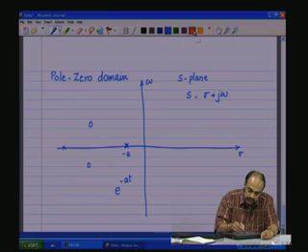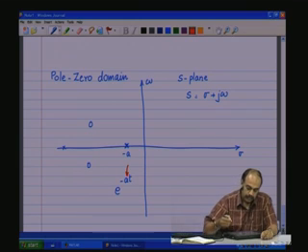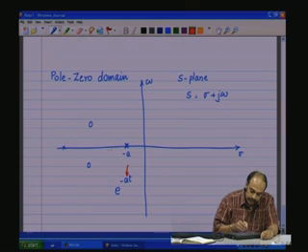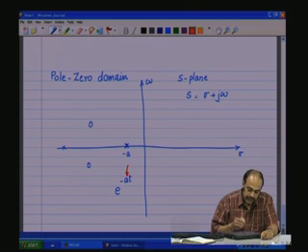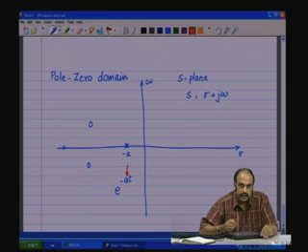So, we know that if there is a disturbance in the system, that disturbance will decay with a time constant which is 1 by a. So, each of the pole points here represents an exponential decay mechanism, such that any disturbance or an excitation will decay at a particular rate.